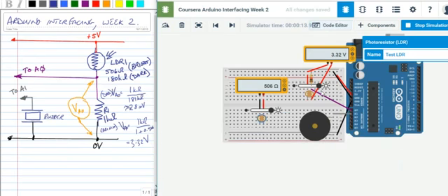Okay, let's get rid of the code. What we've got right now is full brightness. Here's the LDR in circuit. This one is just a test one. We've got the LDR in circuit, full brightness, and as we go darker, we bring this value below a certain threshold, 450.